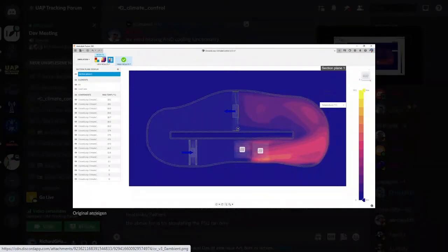I mean, if we talk about using ATX PSUs, they all are around 40 CFM. They all have the same size because of the ATX design, and with the 120 millimeter size, you get 40 CFM rotors. So what I want to say is, it would not change the setup, even if other people buy different PSUs. It would still be the same. And we will still have the same situation that the fan from the CPU of the board will blow into it, adding up the CFMs. So I think from the values, the simulation is correct.